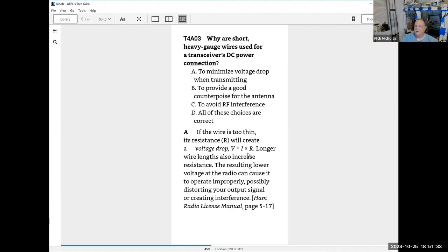If you're wiring your radio in your car, it's a 50-watt mobile radio. And you say, okay, at 50 watts, I'm going to need 4 amps from that previous equation we just did. And you're going to say, okay, well, 4 amps, that's not much.